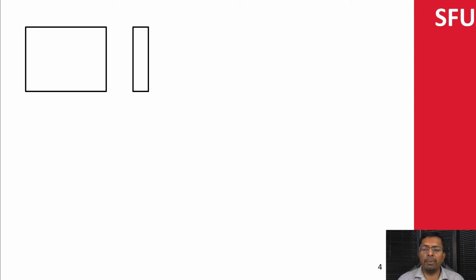At the bottom of the page, we have an example. I'm going to assume that I'm making the back or bottom surface, the surface that you can't see, flat. So I can imagine my arrow going behind, and I'm going to make that surface flat. Already you see the problem: I can't put a label on this front view over here, simply because I don't know if I'm referring to the top or the bottom.